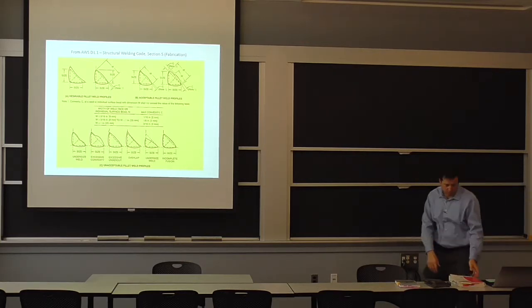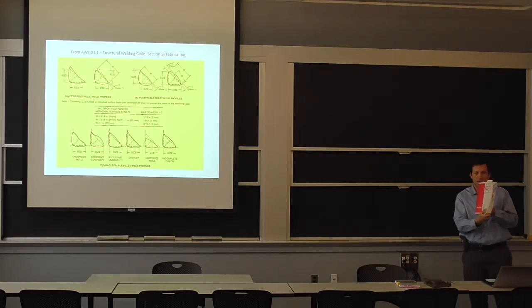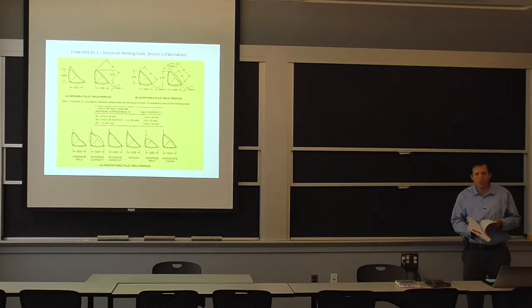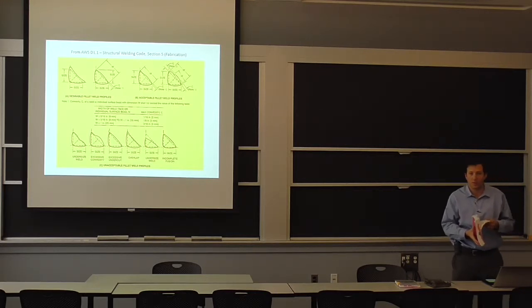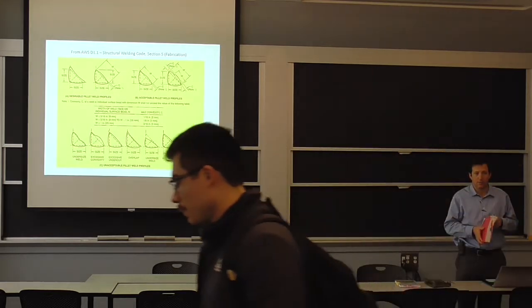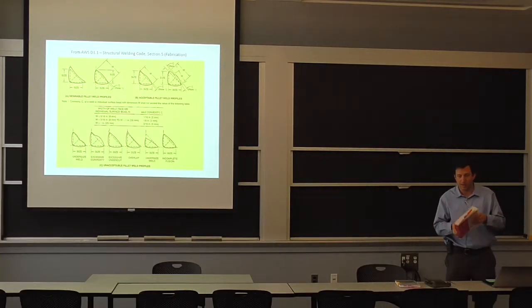So I mentioned the welding code for structural steel, that this is it. This is the one that's got the sections on design of the connection, and then it will go through qualification of the procedure that you decide, the welding procedure. It will also go through the qualification of the welders that are doing the work. So if somebody comes and says, I'm welding for AWS, the welder himself is going to have a certification card, and the inspector also, if it's a certified inspector, is going to have a certification, a little stamp and all that to say that they understand this.